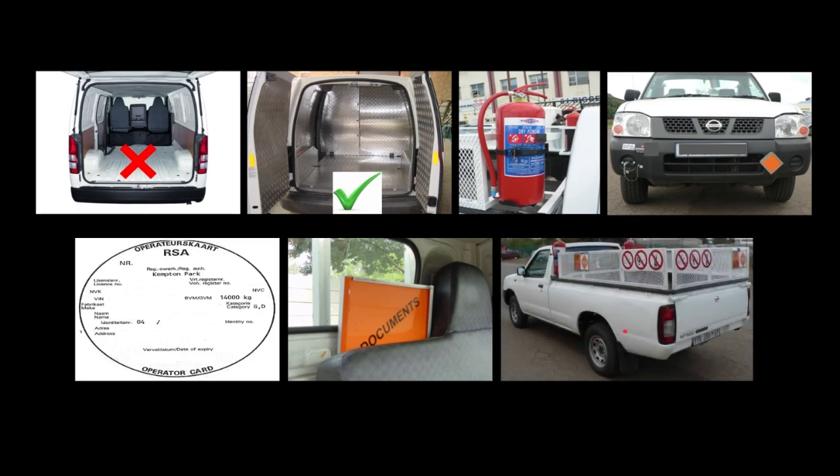Here's a nice example. This vehicle is 100% compliant. Why? We can see there's a placard over there, there's a placard over there, and there most likely is a placard on the opposite side. 3 stickers, 3 stickers, and there will be 3 stickers on that side as well. 2 fire extinguishers. In the front, there should be a hazard warning diamond, and then there will be an operator card on the vehicle over there as well. Then this vehicle is 100% compliant. From here, they can send it to the fire department, remember, to get the permit and to make sure that they can inspect this and say, okay, this vehicle is 100% compliant with the dangerous goods regulations.